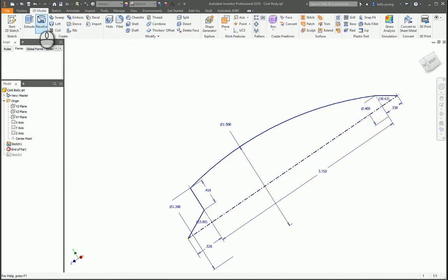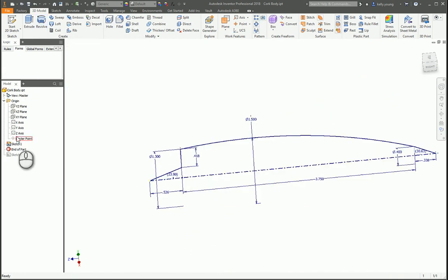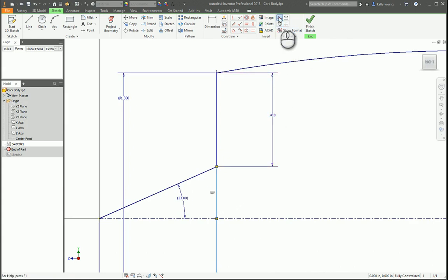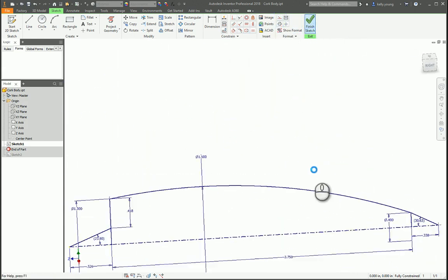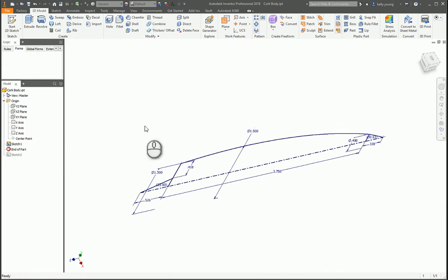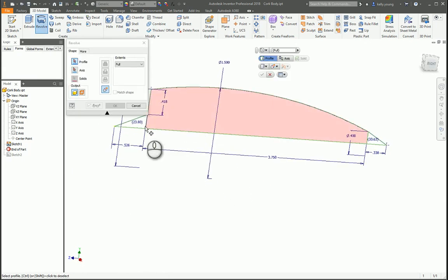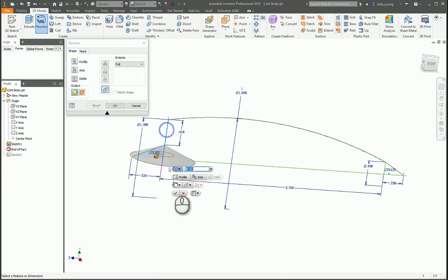So if you leave it on and you revolve it, there's only one surface. And another thing to note is before, when you had this one as a solid and that one as a solid, the thing you'll notice is when you go to revolve it, it doesn't do it automatically because there's multiple profiles. Because you can say, I want to revolve this one, and then you say, well, what axis? Hypothetically, you could select this and that axis.